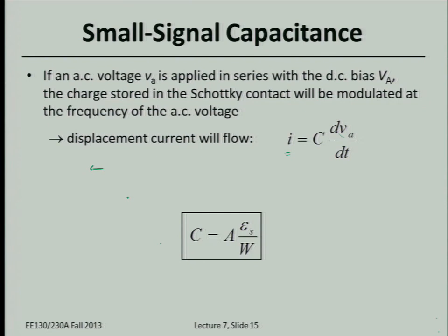It's not a real capacitor. This is not a definition of W. This is the definition of small signal capacitance for a metal semiconductor junction. Right? So the key is that qualitatively the concept is that if you change the voltage, you need to change the charge stored in the junction, and that charge is added or subtracted at the edge of the depletion region, and so the charges that you're adding and subtracting from each side are essentially separated by W, and the dielectric material is the semiconductor.